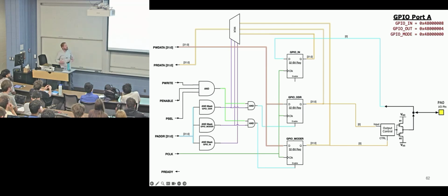The other ones can be read and write because you could write data into the GPIO output port, and forget what it is. You don't want to keep track of it. Then you could read out of it and ask, which LEDs do I have on right now, for instance? Or you could say, I forgot which mode I've set these GPIO pins. Some of them are high, some are low. I can read out of it to understand what those pins are.